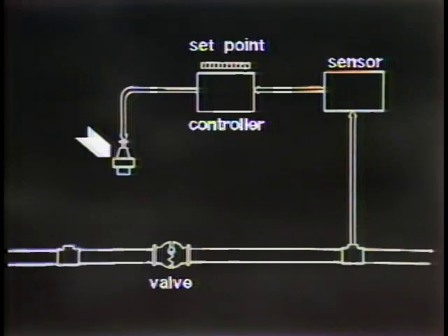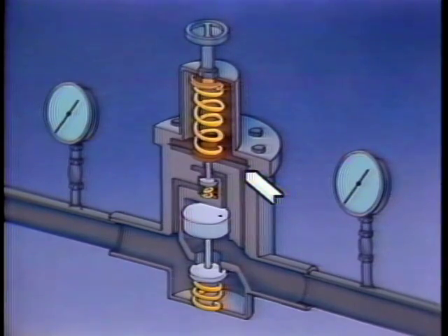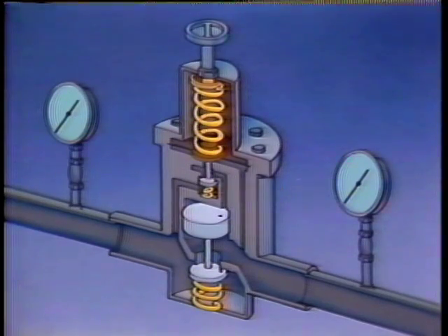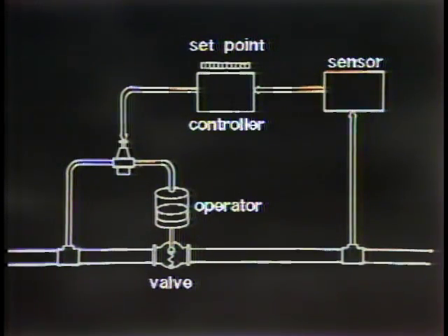of the loop. A diaphragm-type direct-acting valve, called the pilot valve, acts as the pressure sensor and controller. Downstream pressure is channeled to the underside of the pilot valve diaphragm, where it provides a force in opposition to the set point spring compression. A difference between the two forces moves the pilot valve. Inlet pressure is also channeled to the pilot valve. The movement of the pilot valve varies this pressure. It becomes the control signal, which is directed from the pilot valve to the top of a large piston, which serves as the operator of the main valve.